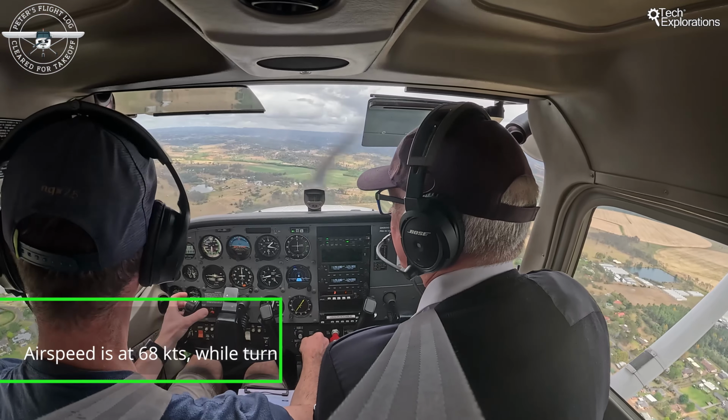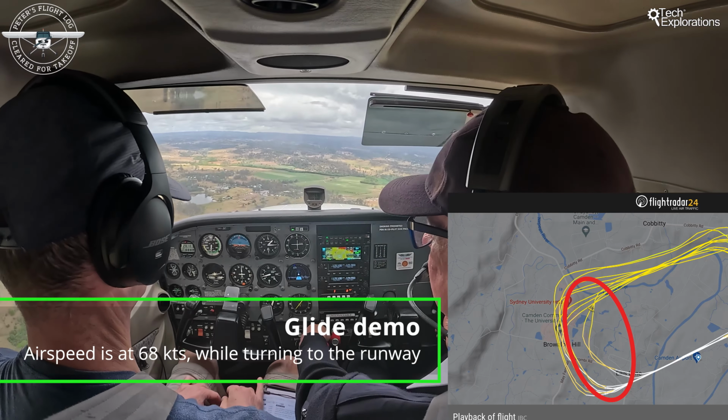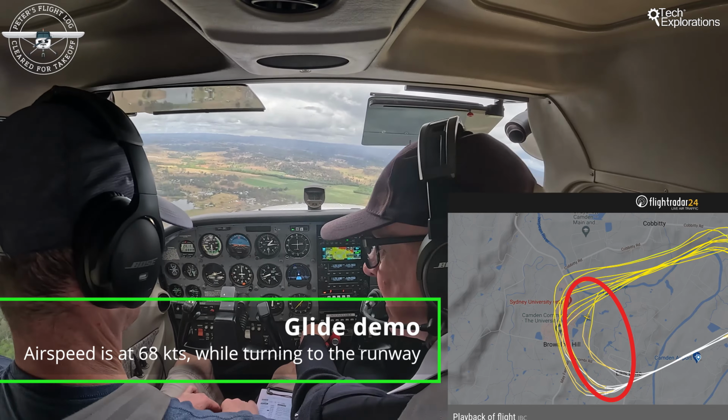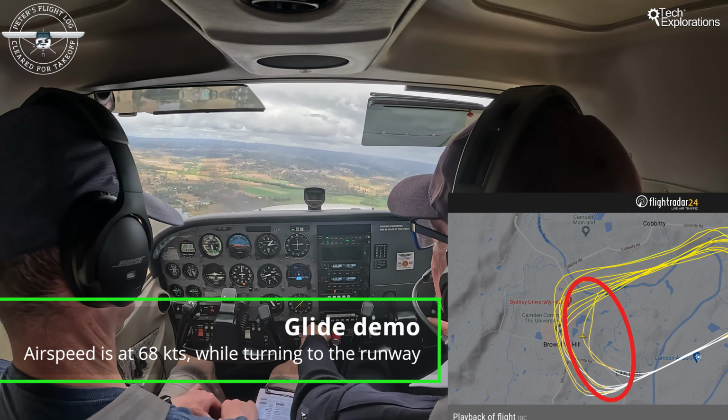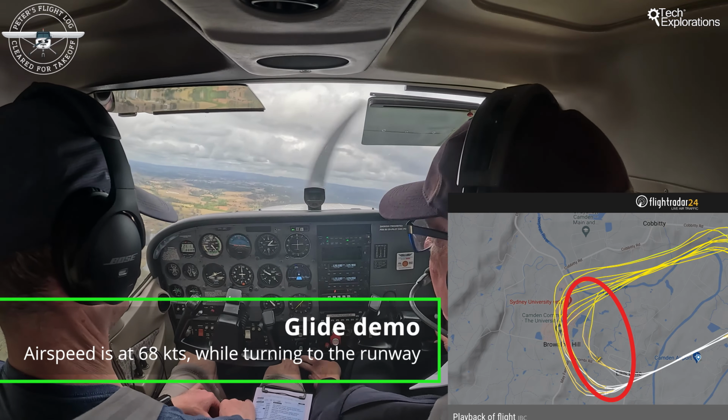So much happened on those two flights. Let's start with power loss and glide approaches. Greg demonstrated this procedure a couple of times and then I practiced a few more. You can see my glide approaches in circuits 5 and 6 in hour 15 and circuits 3, 4 and 5 in hour 16. As you can see in the Flightradar24 flight path for the hour 15 flight, there are two approaches where we cut the downwind short and did a gradual turn into final, skipping base.